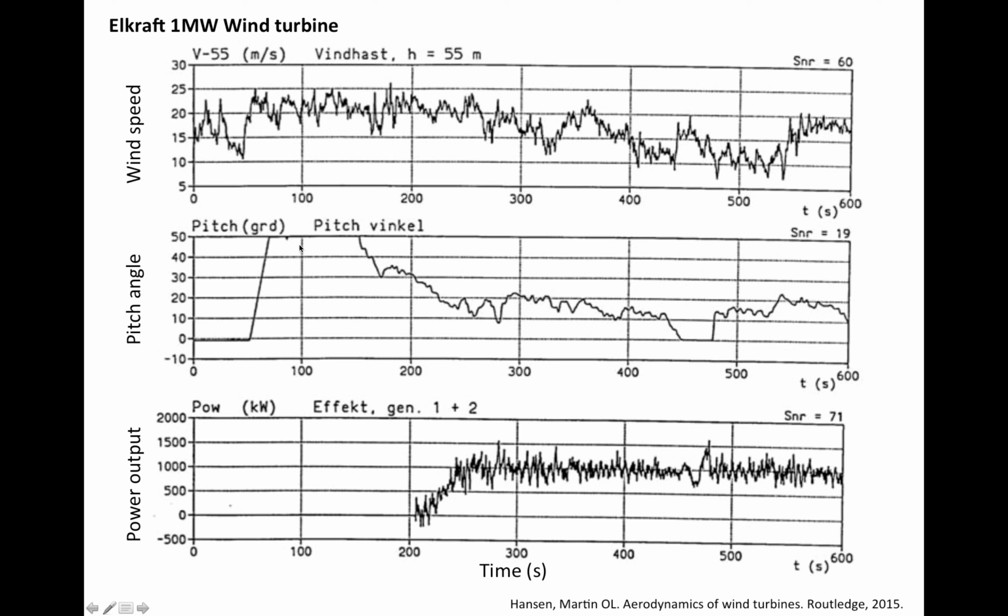because the torque is larger at this kind of pitch angle. Then, as the wind turbine starts to generate power output, the pitch angle is adjusted to smaller pitch angles. Starting from about 50 degrees, it decreases gradually to about 10 or 15 degrees, in this range, when the power output reaches the rated power.